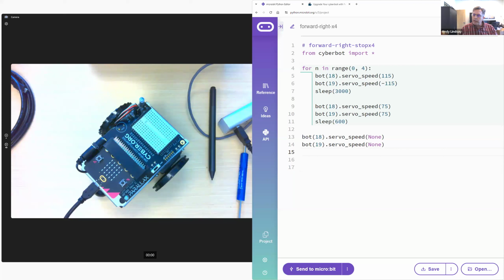Okay, also you can connect via Bluetooth from a smartphone. Now that is true, but the Bluetooth takes up a tremendous amount of memory, and so you end up not having much left for your script, number one. And number two, I have not seen a lot of success. Anybody who uses a tablet to program their microbit uses an OTG connector if they're doing it with the Cyberbot.